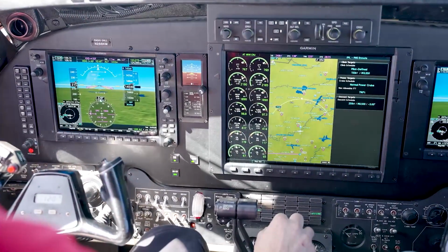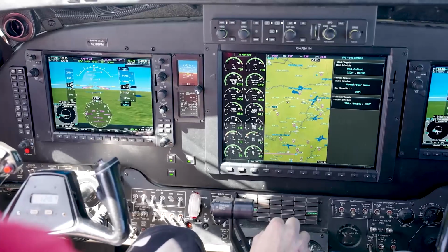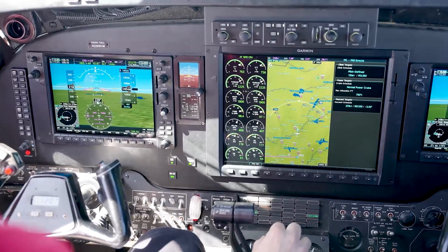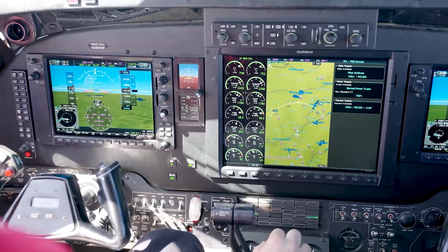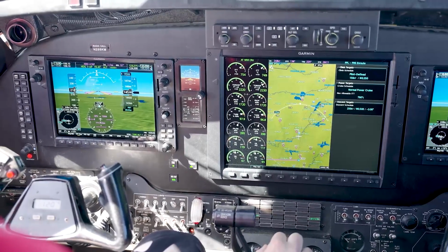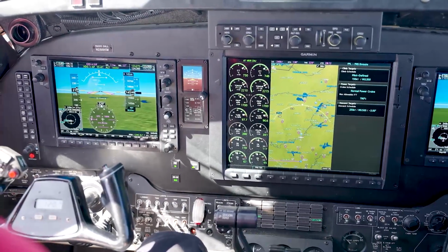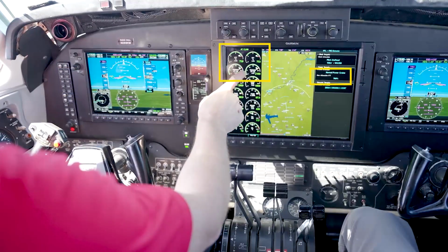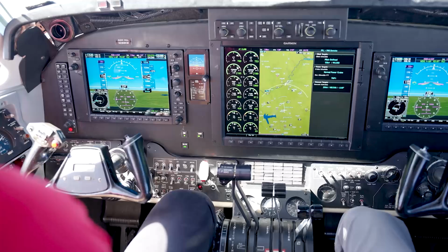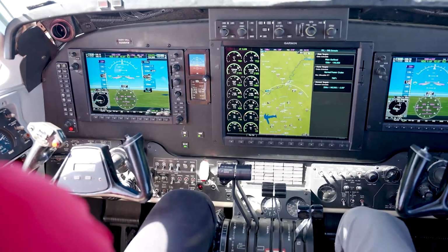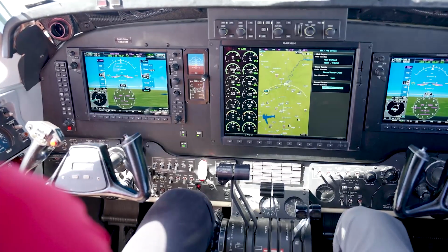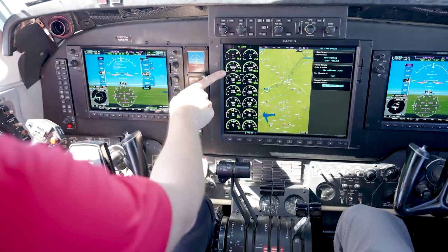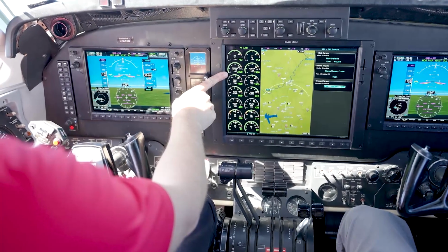The autothrottle is always monitoring torque and ITT to prevent over-torque or over-temp conditions. Torque is limited to 2,230 foot-pounds in all phases of flight, and the autothrottle will make adjustments for RPM changes. The maximum allowable ITT is configurable and is set on the flight plan FMS en route page. If one engine reaches the operating limit before the other, the autothrottle will limit power on the more efficient engine to match the less efficient.